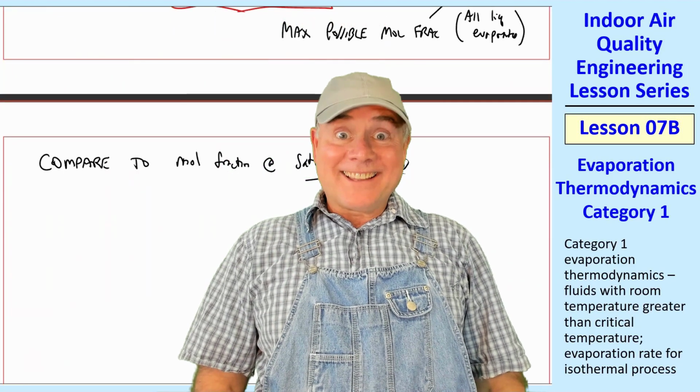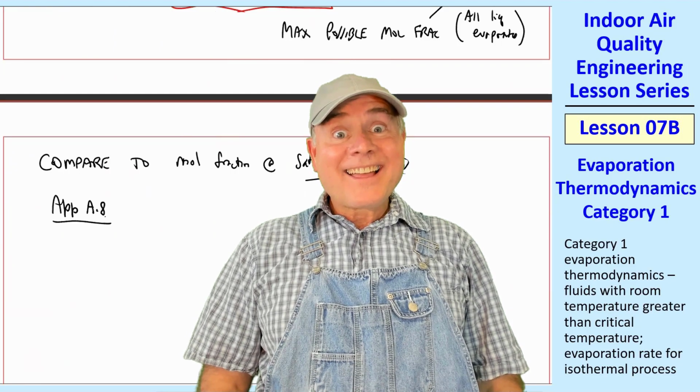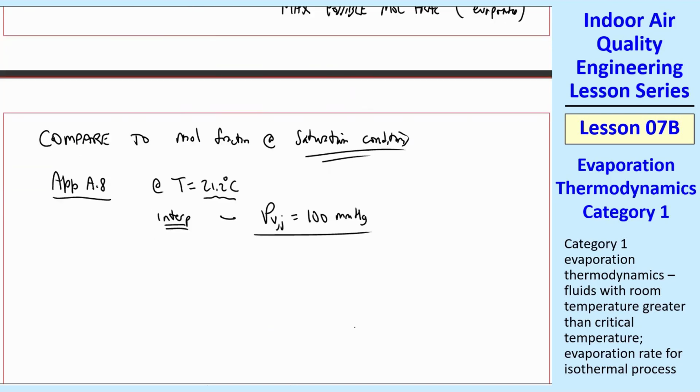How do we calculate that? We go to Appendix 8.8, and at the given temperature, T equal 21.2 degrees C, you have to interpolate. We get Pvj is equal to 100 millimeters of mercury. That's actually one of the numbers right on the table, so we didn't have to interpolate. So Ym saturated would be when Pj is Pvj divided by total pressure.